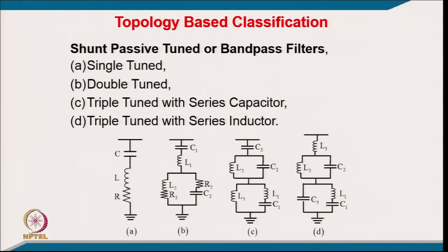Apart from that, you are normally putting a ferromagnetic core, so there will be some core losses in this inductor. But of course, you design this inductor very properly, with a high quality factor. High quality factor means the resistance is quite small. Practically, people are able to realize a quality factor of around 15 to 30. We will explain the quality factor; you might have gone through it in the first year basic course of electrical engineering. We will discuss that further.